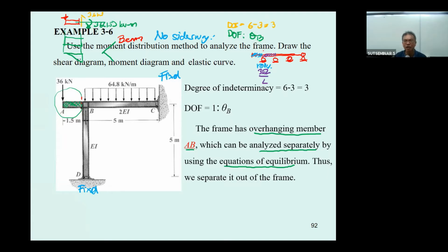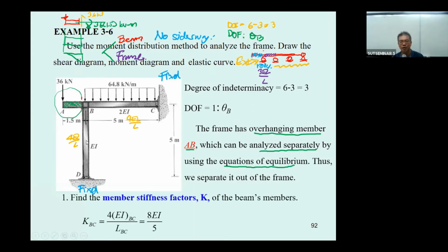But our cantilever for the frame is connected by 2 members. So by doing this, it is not the external roller, it is the member. So we are going to use 4EI over L here and 4EI over L here. The way we consider this problem is different from the way we consider this beam in the previous lecture. And by the difference of 3EI over L and 4EI over L, we will consider it like this.